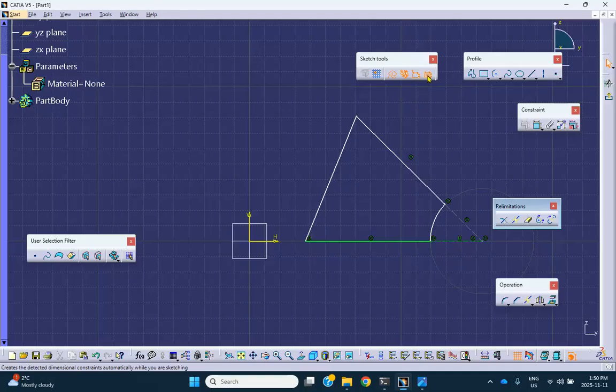Incidentally, I always want these things to be on. Always keep them on. Now, we want a circle on this side. So let's do another arc. For example, here, starting at this end, going like that. But I don't want it to be construction, of course. But I do want to trim this piece, quick trim this piece.